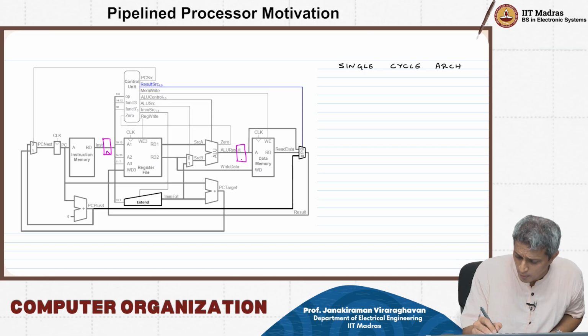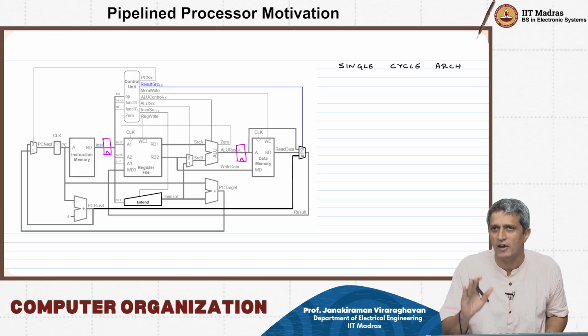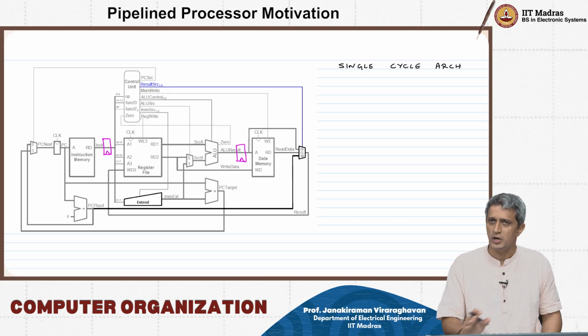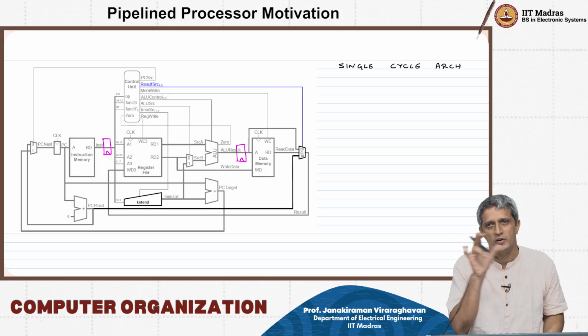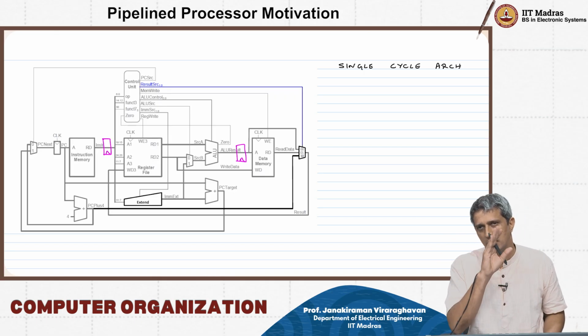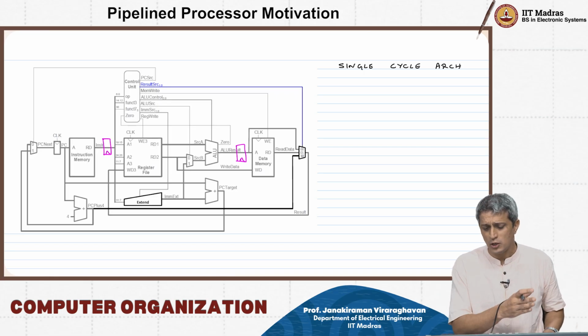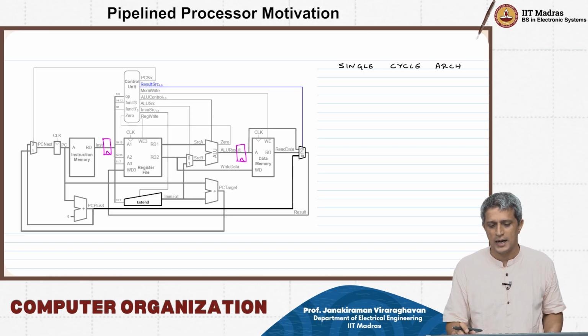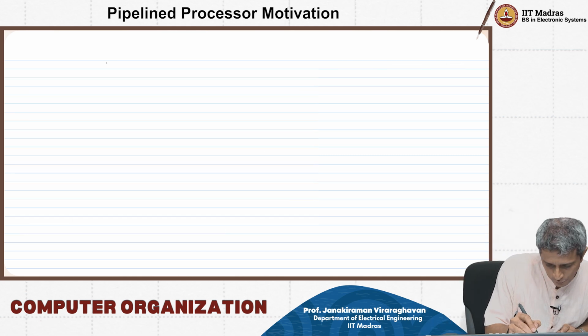This might not be the most efficient implementation, but this is also another valid multi-cycle implementation whose performance will be determined again by the slowest path between the launch and capture flop appropriately, okay. So like that you go ahead and add these flip-flops and we are doing something very interesting. So in the multi-cycle case,